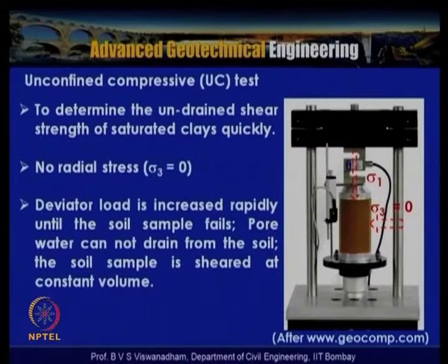The deviator load is increased rapidly until the soil sample fails. Pore water cannot drain from the soil, so the sample is sheared at constant volume, without any change in volume and without changes in the pore water pressure.